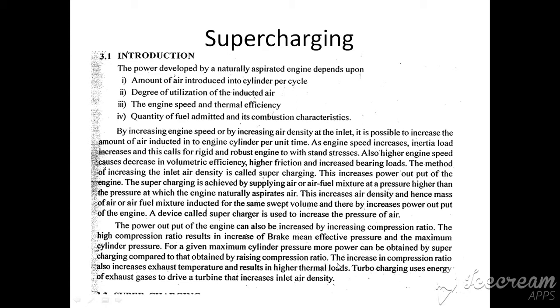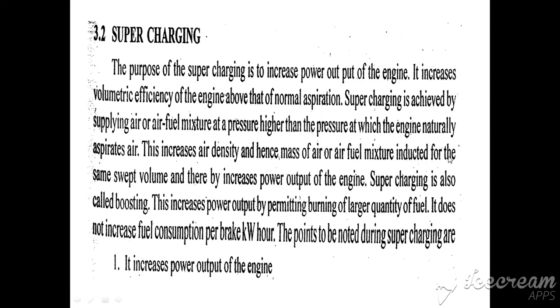So people are going for turbocharging, which uses the energy of the exhaust gases to drive the turbine, which increases the air density. So turbocharging is used in cars, which use the energy of the exhaust gases to drive the turbine, which increases the inlet air density. So again, the purpose of supercharging is to increase the power output of the engine.